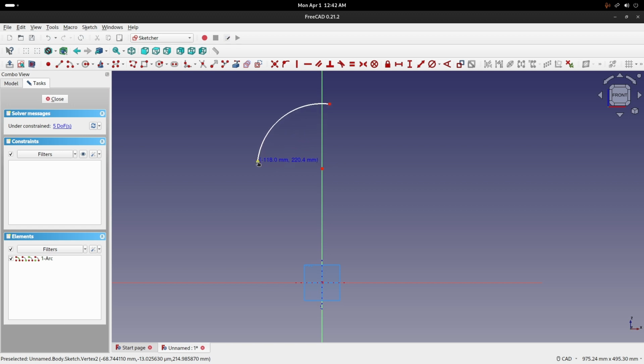You can increase the diameter. You can make it go here. But since we are doing the cross section, we'll just complete the left part of the pawn chess piece, not the right part. The right part, I'll show you a trick how you can complete it by yourself by revolving this sketch of mine. So as you see, this point is not being fixed on this axis.